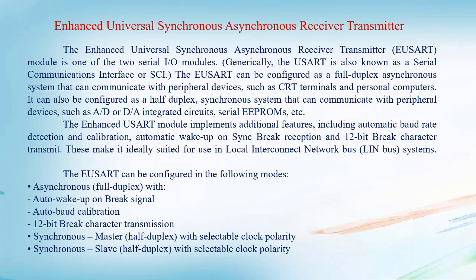The enhanced USART module implements additional features in PIC 18, including automatic baud rate detection and calibration, automatic wake-up on synchronous break reception, and 12-bit break character transmit. This makes it ideally suited for use in LIN bus, Local Interconnect Network bus systems.